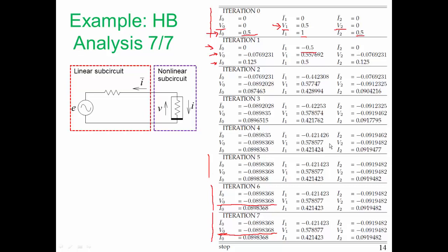Usually with harmonic balance analysis, we find that we obtain a stable solution after just 3 or 4 iterations. It is surprising how fast harmonic balance converges. Of course, as a user, we do not see that. If there is a problem, and it takes many iterations to try and get a steady state solution, that's usually an indication that there is a programming error in the model itself, in that we haven't got the model equations correct.